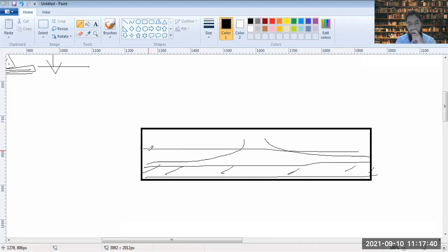Then there will be another pack of this. Then there will be a third pack. So there will be packs or layers filling up the beam, each layer one above the other. If it's a good consistent concrete, I don't think there will be any problem in terms of the flow being higher. But one thing can happen: on the sides of this beam, because the concrete has got more flow, through the gaps it can leak out. There could be a lot of leakage from the gaps here.